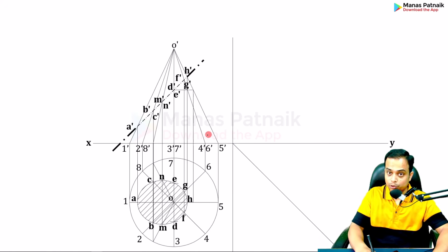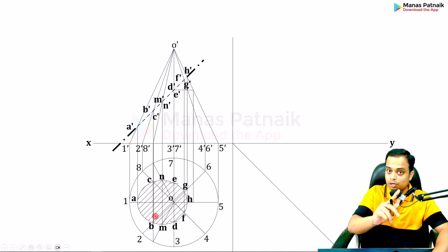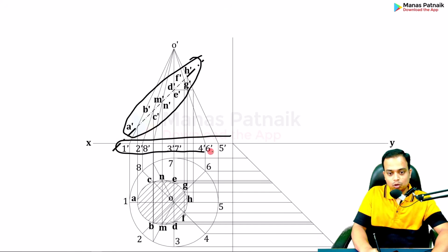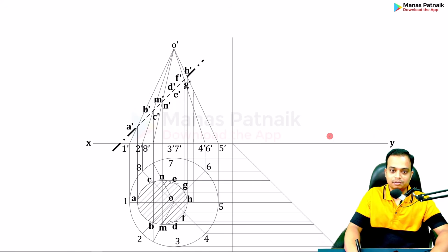Now project the lines through all of these numbers and through all of these alphabets. You should not miss any point. Here it is. And by the way, this angle is 45 degrees. Now project horizontal lines through all of these points. You don't have to worry about all of these points because you can see this horizontal line; even if you make one, it is going to overlap.